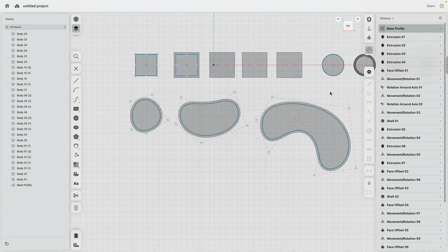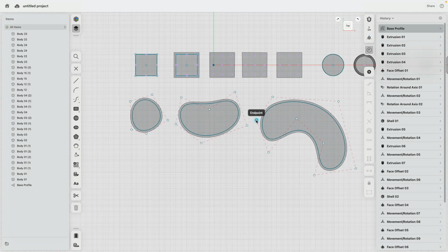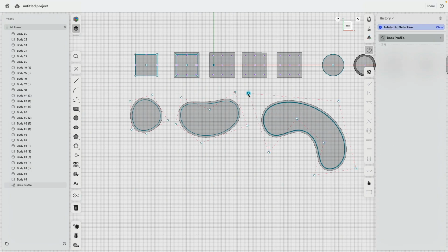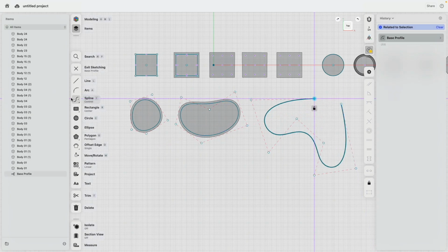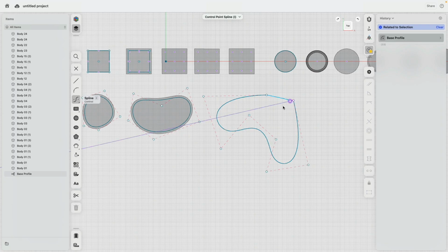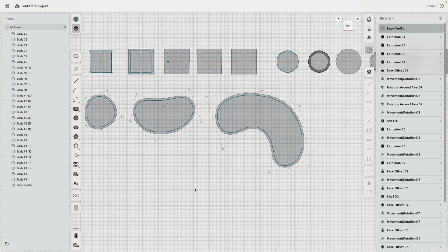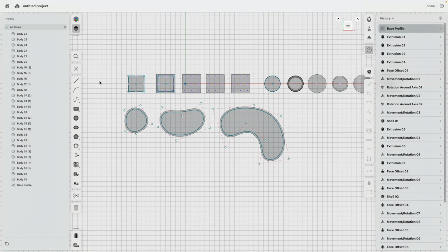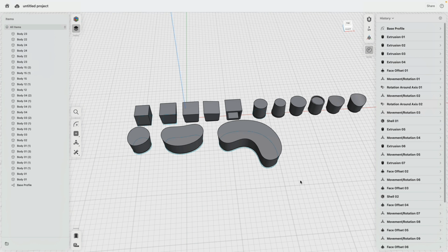I'm curious what happens if I delete this line. Okay. That actually looks cleaner if I delete this point. Yeah, see now here I do think I need 2 points. So how do I do this? I will make this sharp. Then I can open this, drag this one out, go to spline, click, and click patch in a new version, escape and escape, make this smooth and make this one smooth. Bonk. There, that was the last missing piece. Crash course how to use splines. Beautiful. That's actually quite nice.